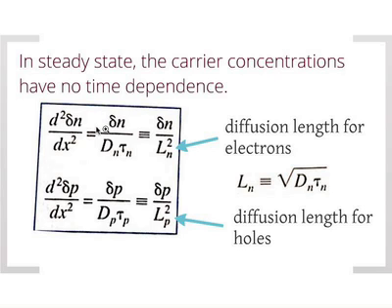Okay, this is the diffusion equation in steady state. And we can also define in this case L squared, where L is the square root of the diffusion coefficient times the lifetime of the carriers, which is defined as the diffusion length. Okay. Now, we saw this partly before, and we will look at this more carefully.